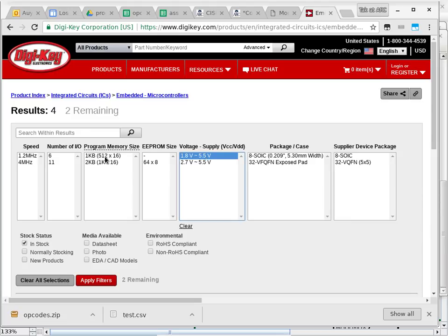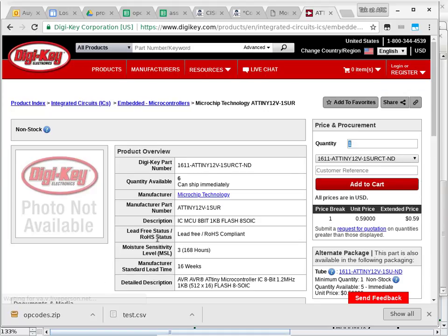And you can also see right here, program size is 512 byte locations. Each location has 16 bits. So I lied, it is not quite as bad as we thought it would be. It is actually 200 and how many locations again? 512, right? Yeah, so 512 locations for opcode. So that's quite a lot. Yep. They used to make parts that are actually smaller, but not anymore.